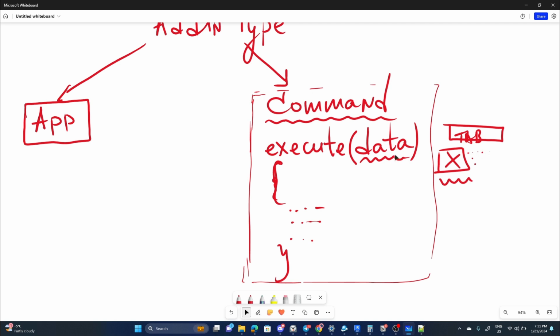I just want to create that command and that's it. So Revit tells you, okay, you can create just a command and we will put it in a standard place. If you're not creating UI for this, Revit will put it somewhere in the standard location, because your users should be able to use your command somehow. If you're not creating your own place to put it, Revit's got to put it somewhere.